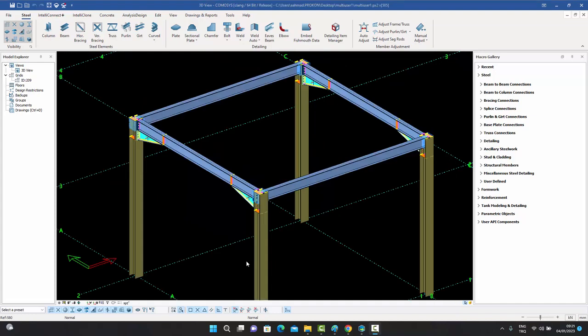So here, for instance, I added the 4 connections in the user 1 model and uploaded my 4 connections, the haunch connections which you're seeing on the screen, to the server. And now I've opened the desktop, the user 2 model. The user 2 model is now open, and I just download it from the server, and I have just managed to download the 4 connections, as you can see on the screen.